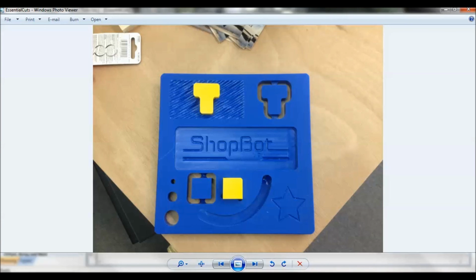This is a texture here, a texturing toolpath. And again, here's with our inlay to get that to fit. This one here is a fluting toolpath. So there's a lot more different types of toolpaths than the two that we covered today. I would go in and play around with them, check them, see them in 3D preview and 2D preview. What you're going to see on your machine is what you're going to get.